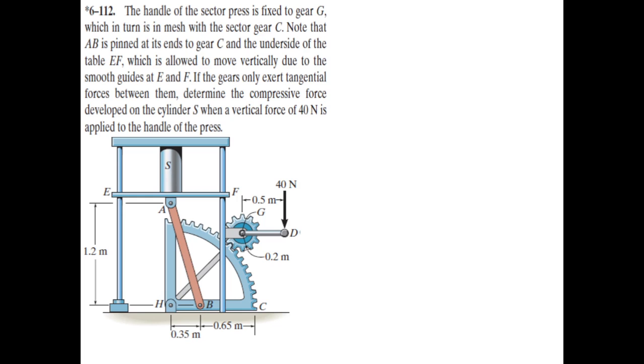So we know that while we were solving the problem on truss structure, we used the method of sections. And when we solved the problem on frame, the method that we adopted was to dismantle the parts. So we disconnected different parts, and then we analyzed each and every part by using equations of equilibrium. So the same strategy is used in solving problems on machines. We have to actually think of dismantling or disconnecting these members one by one, and thereby calculating the unknowns, so that the problem is never statically indeterminate.